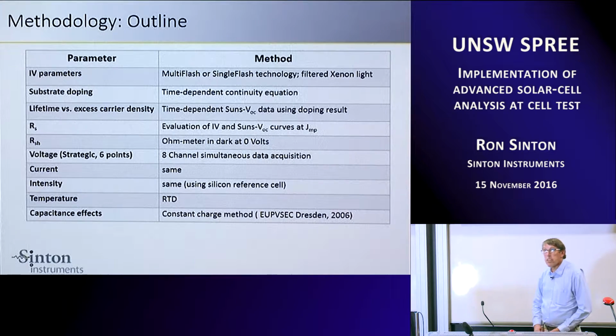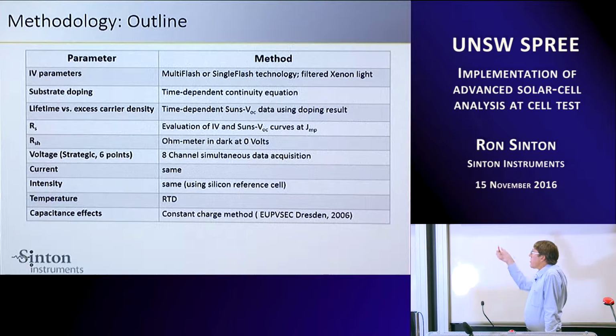So the methodology that we use in this IV tester is that we measure the IV parameters with a multi-flash or a single flash technology, as I said, under filtered xenon lamp to be class A. We measure the substrate doping with the time-dependent continuity equation. It's basically just accounting.